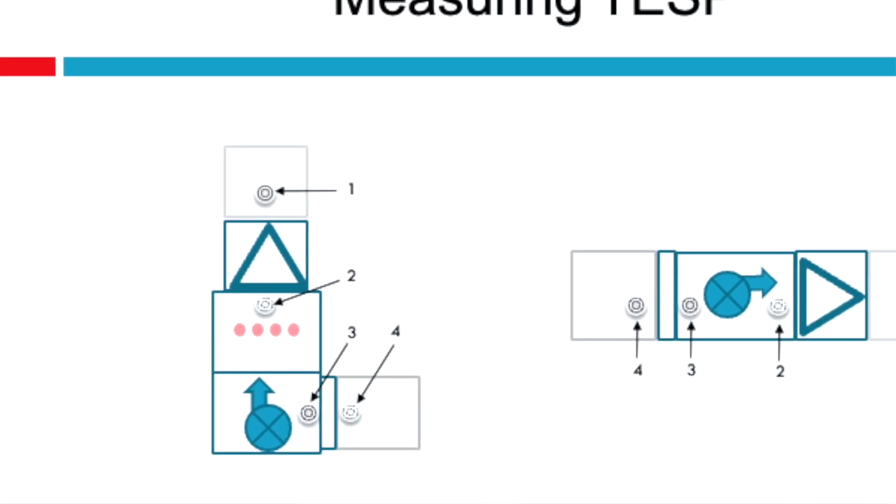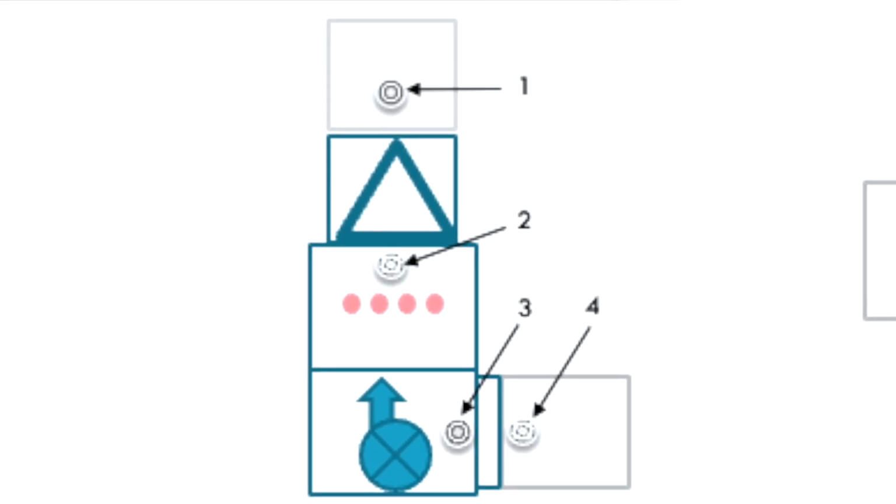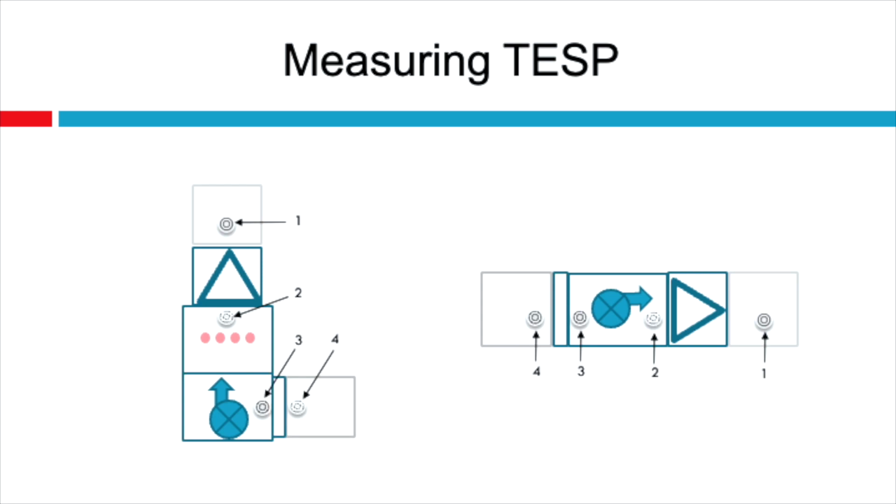This is a little tougher when we talk about a furnace with an AC add-on. So as an example, with a furnace with an AC add-on, you need to measure prior to the A-coil on top of that furnace because that is not shipped in the box with the blower. Now me personally, I would turn the system off, take the high limit switch out, put a piece of tape over it and stick the probe through there because it's prior to the A-coil and typically near the heat exchanger. So you're able to pick up all of that external static pressure without overestimating what it actually is in the supply.